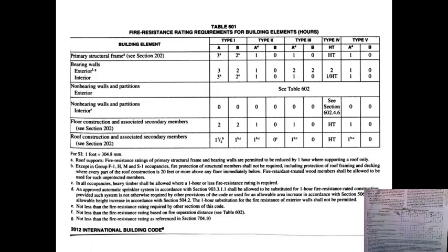Type 1 and Type 2 constructions. You'll see that information if you look on page 107. It describes what those requirements are. Types 1 and 2 constructions are those types of construction in which the building elements listed in Table 601 are of non-combustible materials, except as permitted in Section 603 and elsewhere in the code. So you have steel and concrete construction.